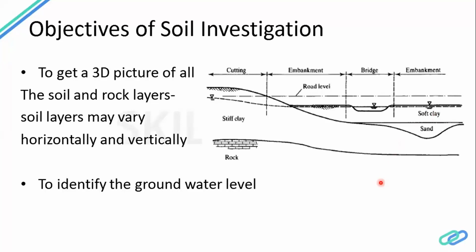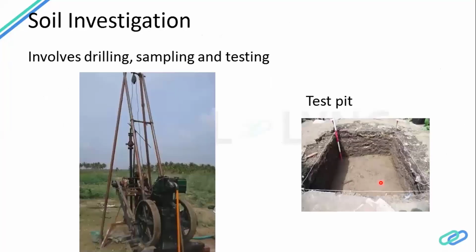Also, we have to identify the groundwater level, which is very important in our determination of the foundation. These are some common tests. Here we can see the most common method, the standard penetration test, which is being used all over the world. And this is a test pit. In the standard penetration test, we get the penetration resistance at different depths. Also, it is possible to collect samples.